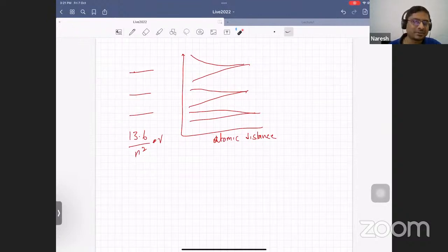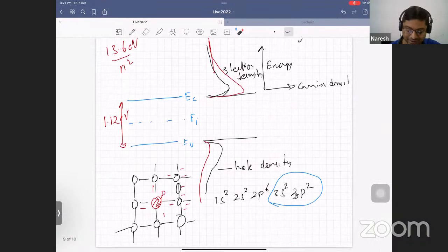Well, no. See, remember, we are not doping phosphorus in the conduction band. We are doping the lattice, the structure, right? We should not say we are putting an atom in the conduction band. We are putting an atom in the lattice, and as a result, the electron is in the conduction band. I'm just clarifying that, we should be precise when we talk about it, okay?